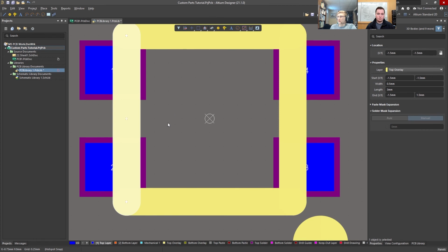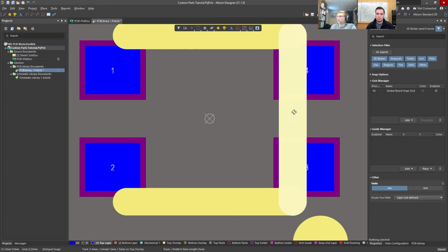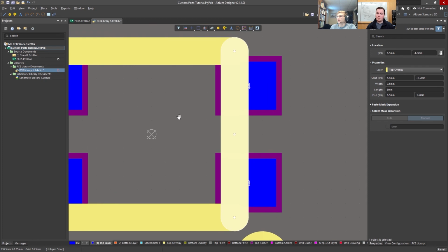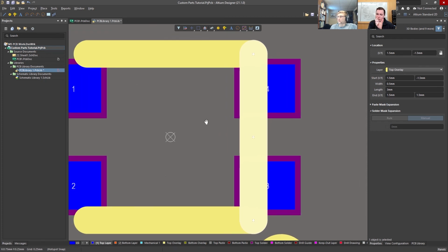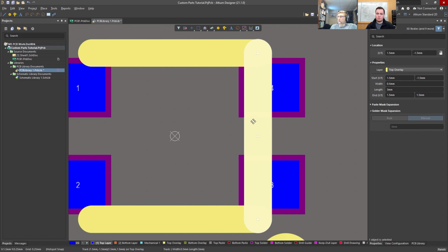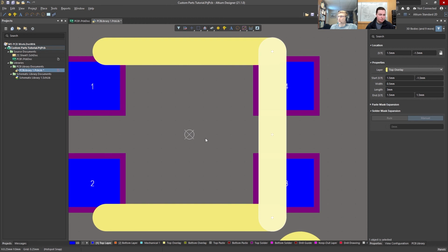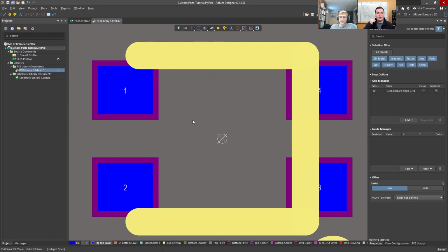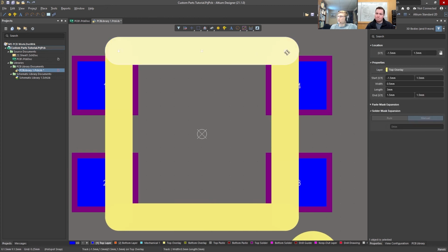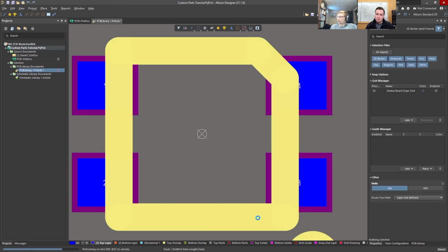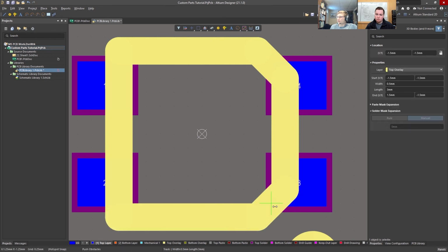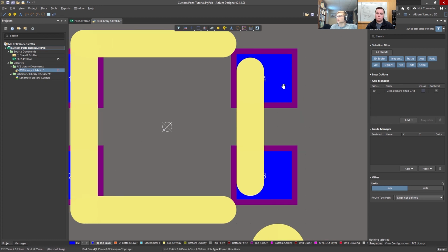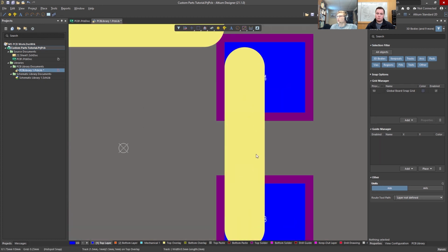So we're probably not going to get to use these lines, or if we are, we're going to have to adjust them significantly. I'd say let's make them shorter so that we have horizontal alignment. So you want to put them in the middle between the pads? Ideally. You don't have to, but I think it would make it easier and less prone to error if you can see it, although they might not even print. Alright, an efficient way to do that is to start a little bit of a chamfer, like this, and then just delete the chamfer segments. That way you break the connection between the horizontal and vertical. And then you can start dragging them in.